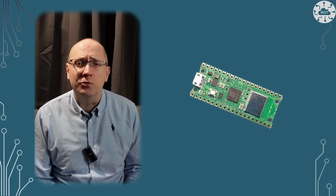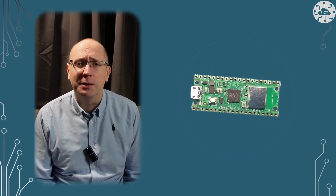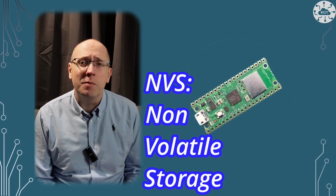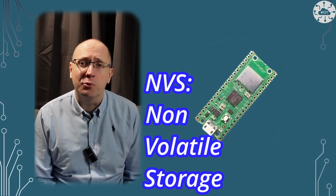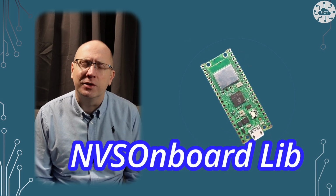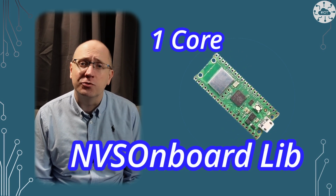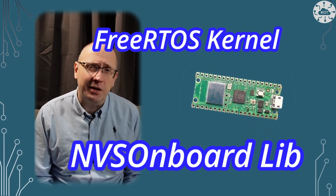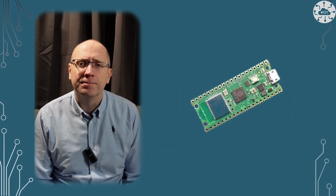Working with Flash using the base level functions on the API requires quite a lot of design work. What we miss on the Pico is a great library like the NVS library available for the ESP32 microcontroller. So I've produced a library inspired by the NVS library. It handles single core, multi-core and the FreeRTOS kernel in a single core situation. More on that later in the video.